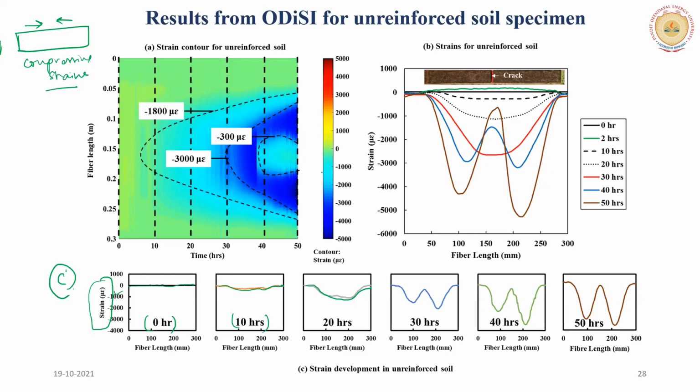Now, you look at the image number 30. So ideally, this graph should have gone like this, but suddenly at a point, you can see that there is a dip, right? This dip. And this dip is nothing but the location of your crack. So this crack location will show you at what point there is a crack occurring, right?